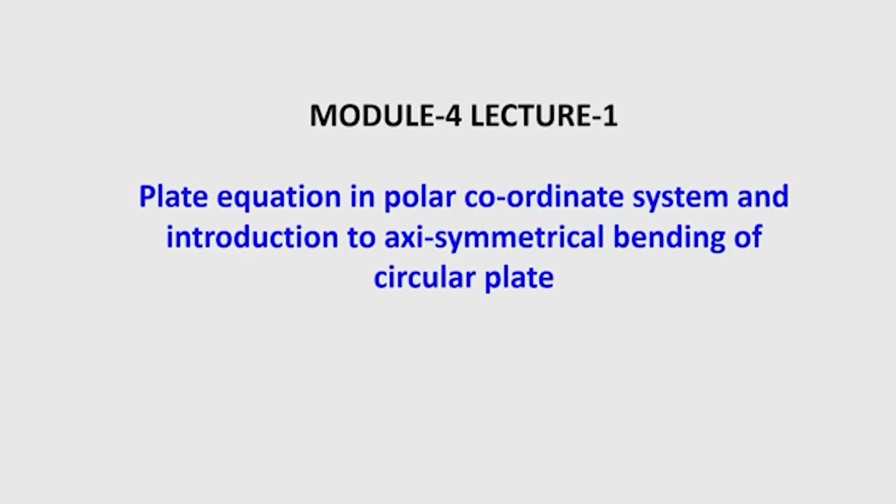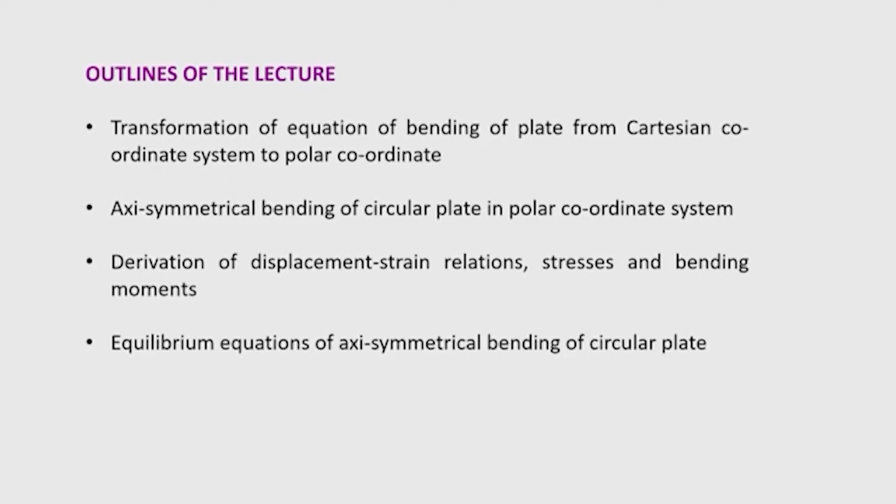So, today our discussion will be the governing differential equation of the plate in polar coordinate system and an introduction to axisymmetrical bending of the circular plate. Specifically, we will use the polar coordinate system for the circular plate problem. Today I want to cover the following topics: transformation of the equation of bending of plate from Cartesian coordinate system to polar coordinate system, then axisymmetrical bending of circular plate in polar coordinate system, then derivation of displacement, strain relations, stresses and bending moments.